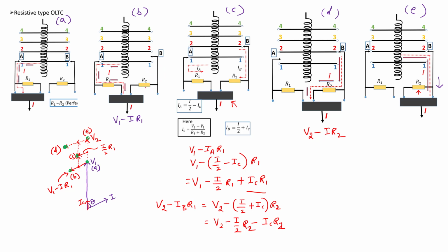Simply consider case B here. In this, one of the arms, B, is lifted, right? Now the voltage between B and 1 when it is lifted is of importance, because sparking etc. depends on this voltage difference between the lifted arm and the approaching tap, or the lifted arm and the leaving tap. So these voltage drops are important.